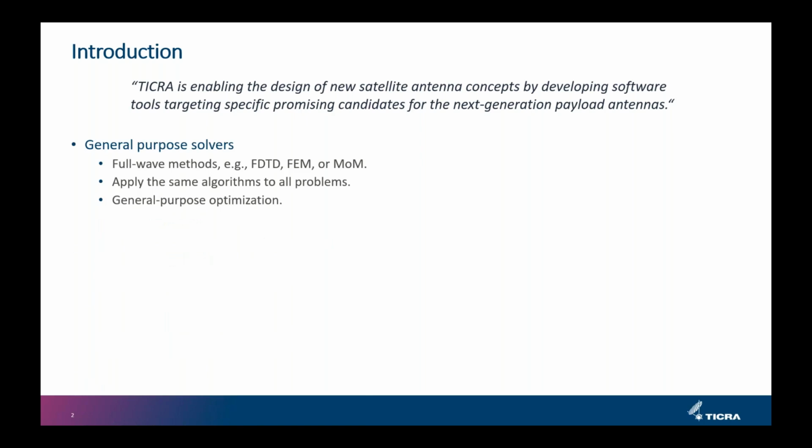Well, typically you will have your general purpose solvers. They will typically use full wave methods such as the finite difference time domain method or the method of moments, and they'll apply the same algorithm to solve any electromagnetic problem you want to solve in that program. And they'll typically also have some general purpose optimization algorithms in there.